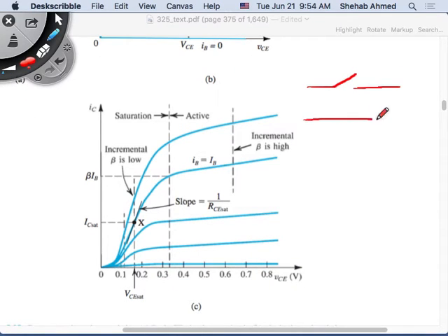open circuit or short circuit. But when it's a short circuit, there's a drop. What is this drop equal to? It's an equivalent resistance multiplied by the current flowing through it. This resistance is now very small because of the slope here being very high. Here we zoomed in considerably on the saturation region. So when you want to operate as a switch, you either operate in cutoff, open circuit, or you close the switch and operate with a small voltage drop.